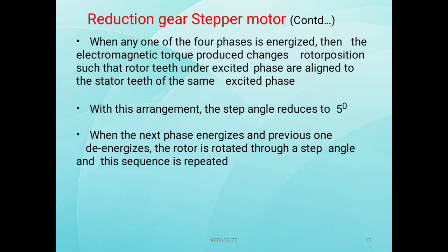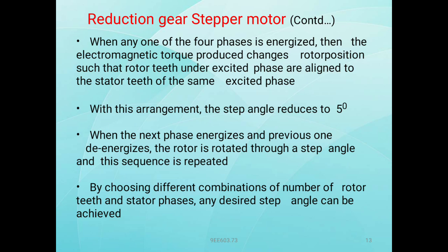When the next phase is energized and the previous one is de-energized, the rotor is rotated through a step angle, and this sequence is repeated.